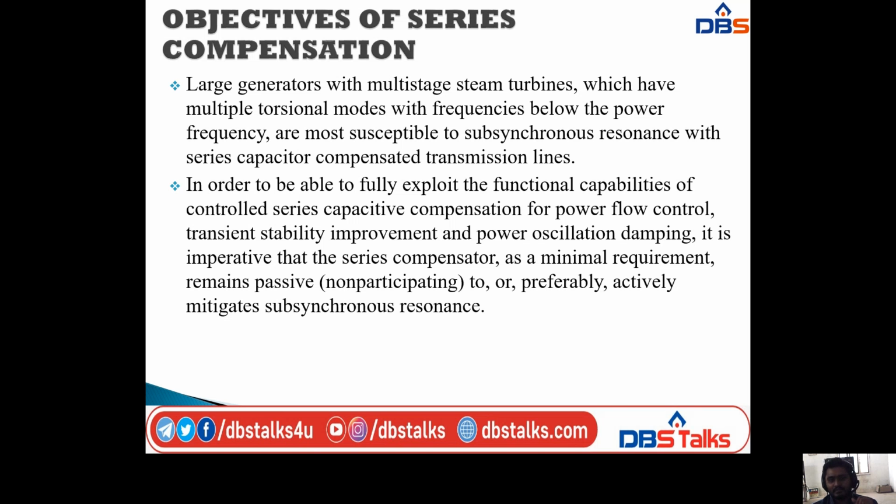In order to be able to fully exploit the functional capabilities of controlled series capacitive compensation for power flow control, transient stability improvement, and oscillation damping, it is imperative that the series compensator, as a minimal requirement, remains passive, that is non-participating, or preferably actively mitigates the subsynchronous resonance.